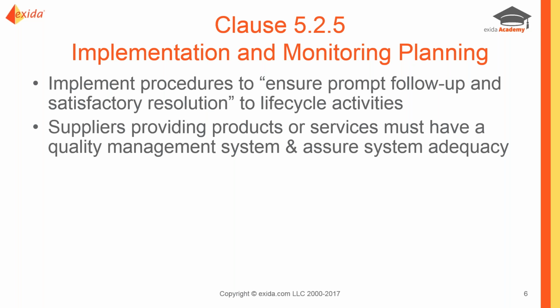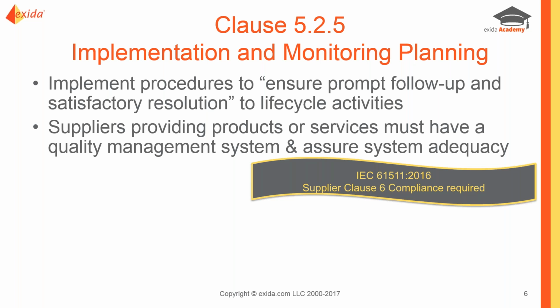The life cycle activities that we need to follow up on and work through at this phase include your process hazard analysis, risk assessment, auditing, verification, validation, functional safety assessment, and then of course any post-incident activities that we have.